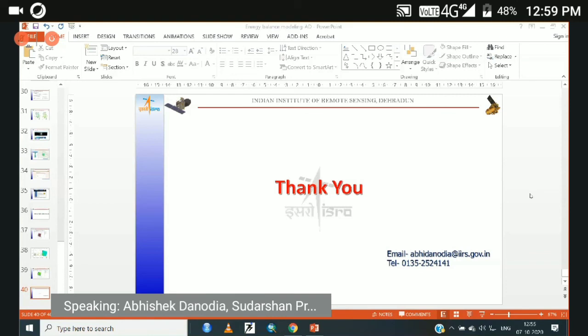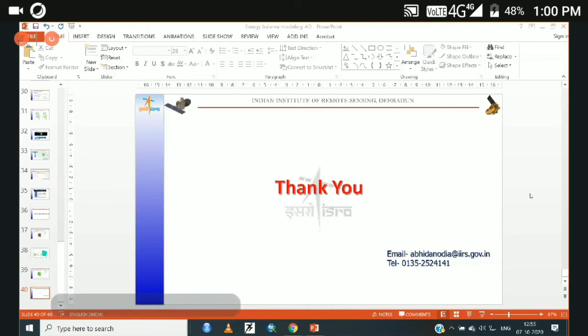If I want to do a complete classification of Bihar state, a single MODIS satellite image can cover the complete state. But my MODIS data set has a spatial resolution with a pixel size of 250 meters by 250 meters at finest. And when we go for classification, at least a 3 by 3 window has to be confined to a particular crop or the same type of class. So 3 pixels by 3 pixels means almost 750 meters by 750 meters has to be the same kind of crop. Then you can completely define it as a particular crop type.